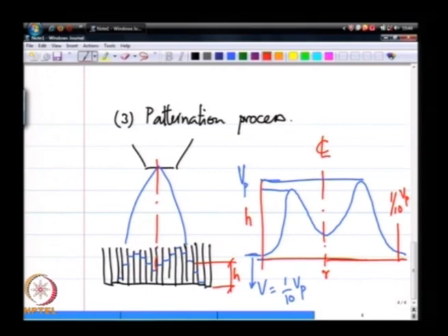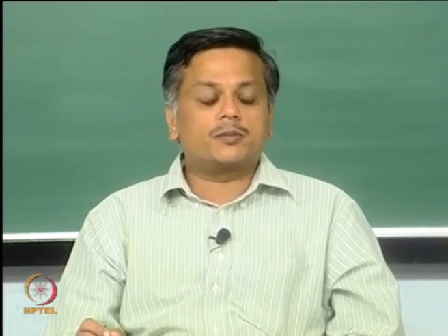So, once I know this, I can essentially do what we did with the image. So, I get a pattern at one axial location, pattern at another axial location, and from that, knowing the spray edge at the two axial locations and knowing the origin of the spray, I can fit a second order curve to these 3 points and from that calculate a spray angle.